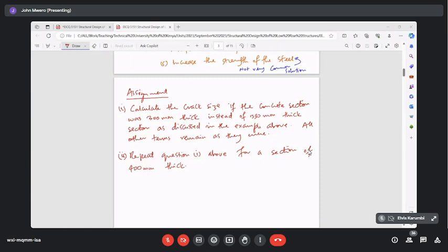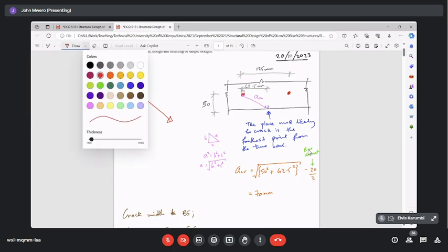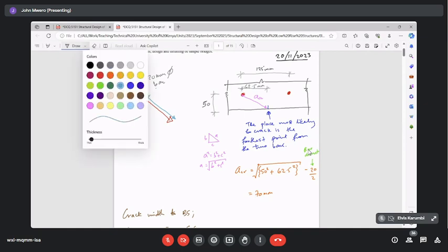Any other question? I meant when calculating ACR. ACR, yeah. No, it's a bar size. The 20 is bar size, and we are dividing it by 2 so that we remove the radius. That's your bar. We've calculated that. But the distance we want is that. This bar is 20 millimeters. So we subtract half of that so that we get this distance, because it's the one we want.